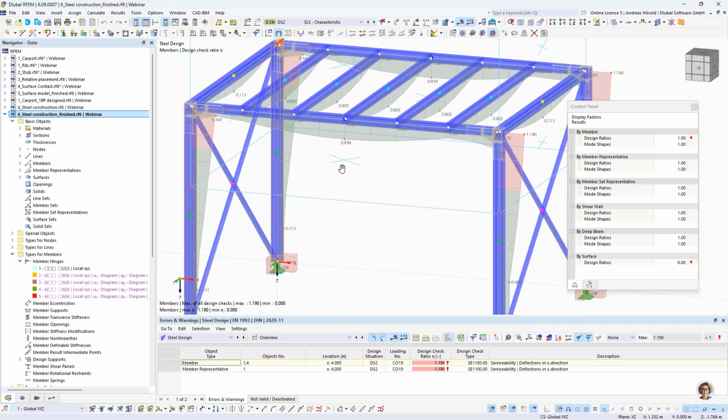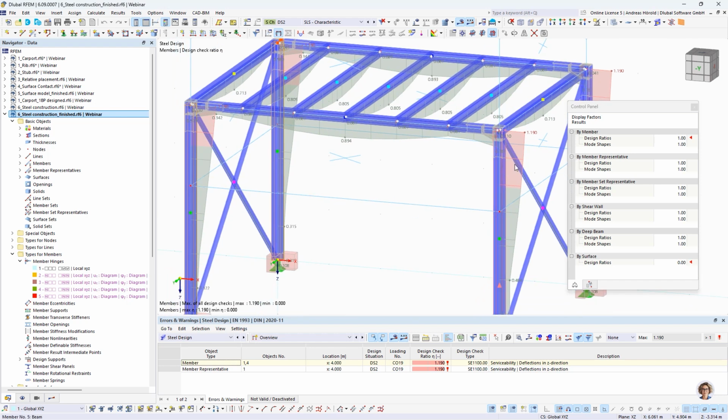I think you have to consider such stiffness reductions, because otherwise the stiffness in the horizontal direction is too large, while the construction is actually weaker and can swing a little bit. Now you have the possibility to consider such joint stiffnesses in your global model.